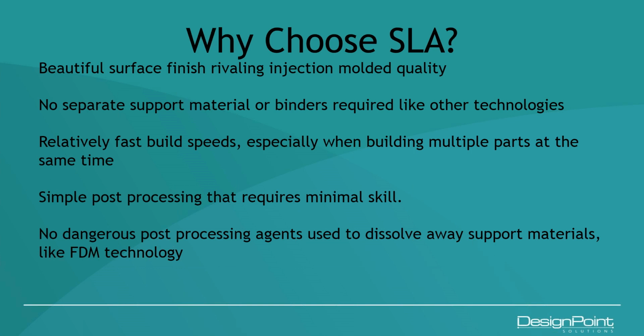Like I just said, like FDM technology, you use sodium hydroxide. For the SLA technology, that's not required at all. It uses very green cleaning agents to create a bath to clean the parts. You don't have to worry about caustic chemicals that could potentially burn the skin. And there's no special facilities requirements. It is truly office friendly.